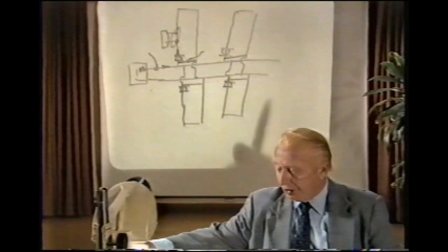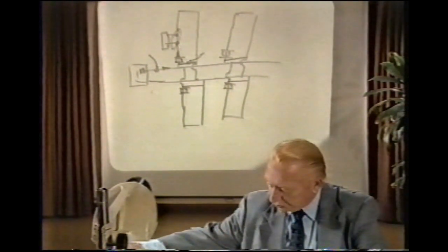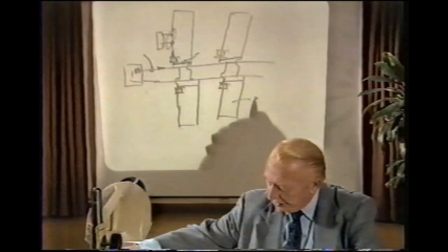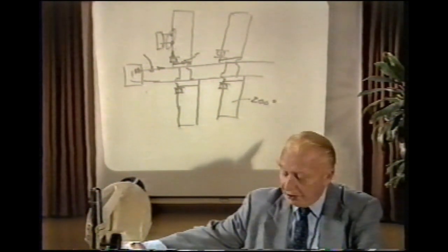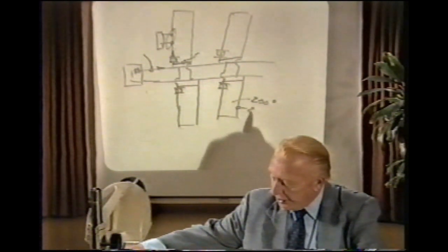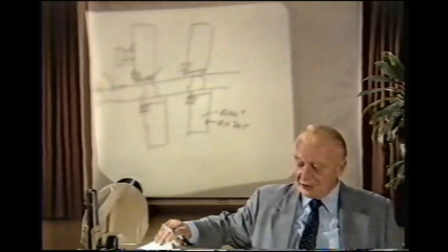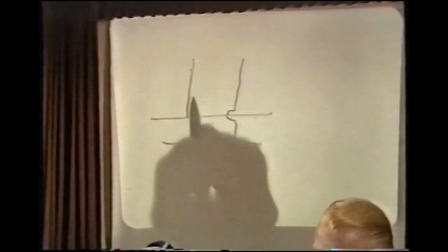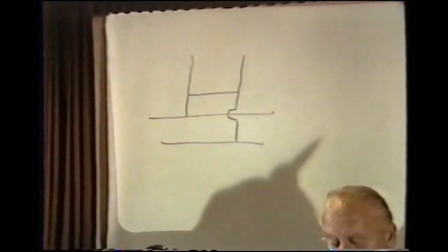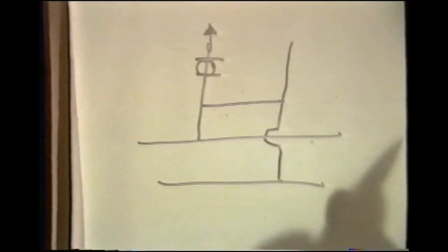To illustrate what was done in this example, the original systems were designed for 200-degree water temperature and designed for a 20-degree delta T. So let's look then at one of these buildings in terms of application as related to primary, secondary pumping flow mix. We came from the distribution main, provided our common piping, and established with the secondary pump the necessary flow rate through that particular building.